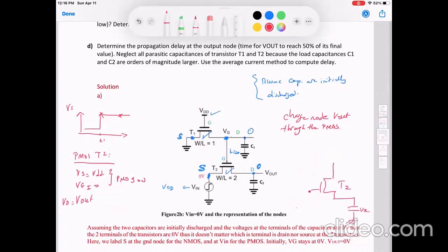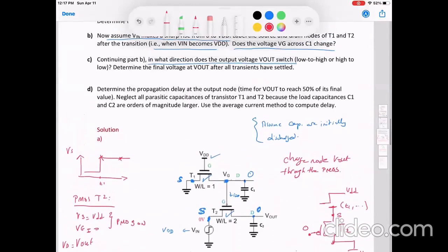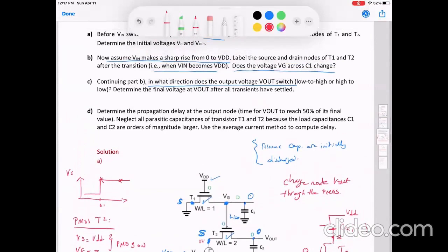Here this is always 0, this is the PMOS, and now S after T1 is really VDD, between T1 until the end, because this is a step function. This is S. So the final value for Vx is going to be VDD in this scenario, because throughout, VSG is greater than VTP. So it will pull this node up to VDD. Great. Now, determine the final voltage at the output.